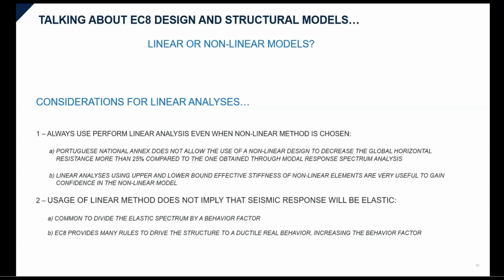And on the other hand, it is also very important that when we use linear methods, meaning when we analyze linearly, this does not imply that the response we obtain, the seismic response, is linearly elastic. There are other topics, details, and variables that we introduce into this calculation, such as the behavior factor that is used to modify the elastic seismic spectrum, and many other rules that Eurocode 8 imposes for the structure to have a ductile behavior and allow us to amplify our behavior factor.